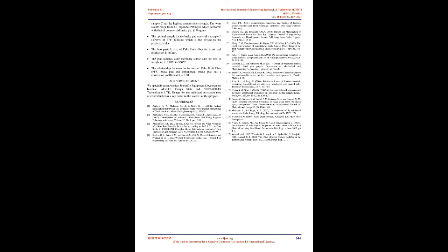of the brake pad. Again, from the result generated showing the contour diagram of the relationship between 3 variables, i.e., palm fruit fiber, A, and binder, epoxy resin, B, to the hardness value of the samples developed for the brake pad, Figure 6, it can be inferred that the value of the correlation coefficient, R, is about 0.78 for A while it is 0.49 at B. This shows that PFF contributes more in terms of wear resistance for the material developed. Figure 6 shows the 3D surface plot of the relationship between 3 variables to the compressive strength of the samples developed of the brake pad.